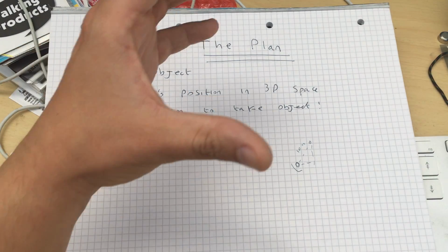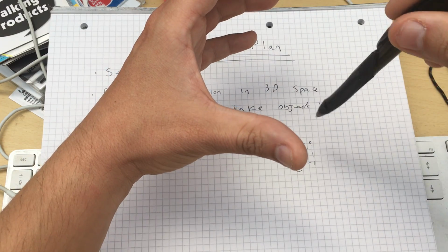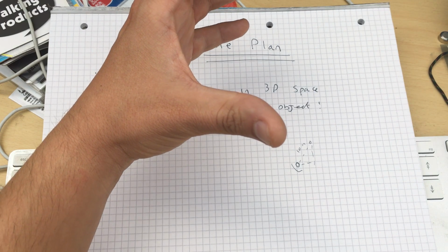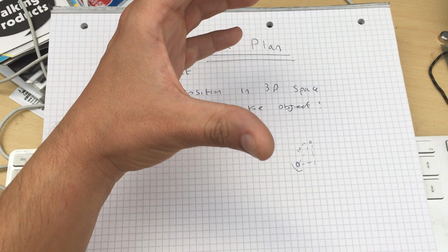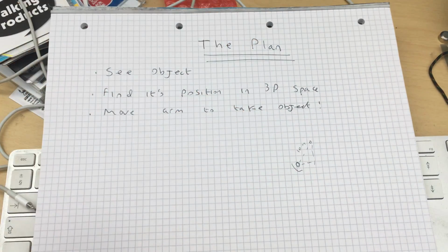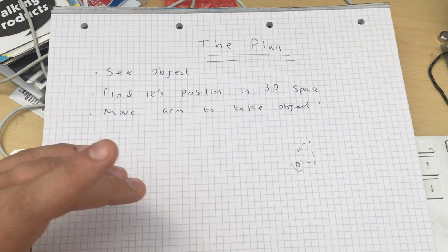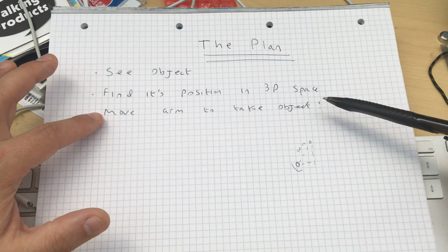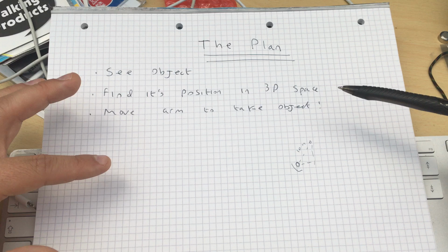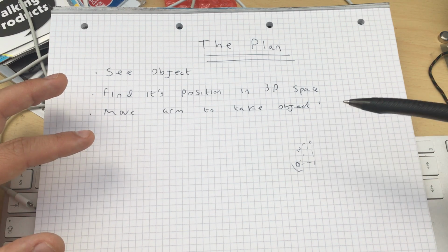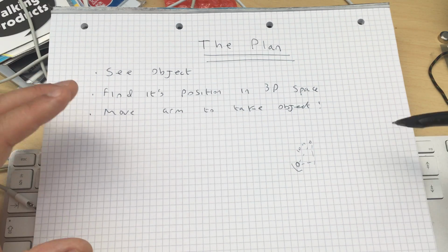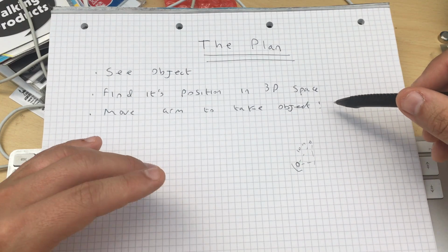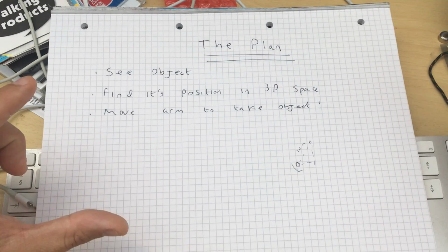So if I need to grab something here, imagine this object is here, and one arm segment is, I don't know, 30 centimeters long and the other is 20 centimeters long, what angles do I need to rotate the joints to grab that object? There are much better explanations of this stuff. As I said, I'm learning this, and this is how I'm trying to break it down. With the inverse stuff, I've played about with trigonometry and the SSS triangle, where you can build a triangle that doesn't have any right angles in it, and using that I can work out where this object is.